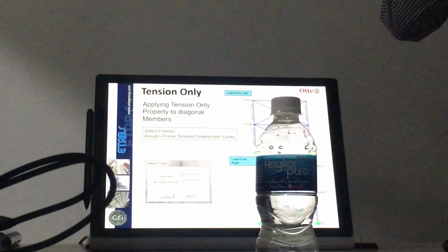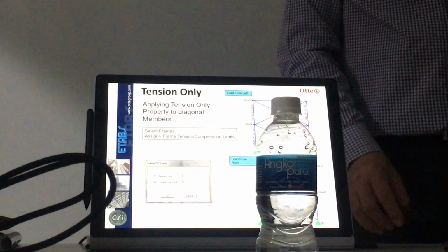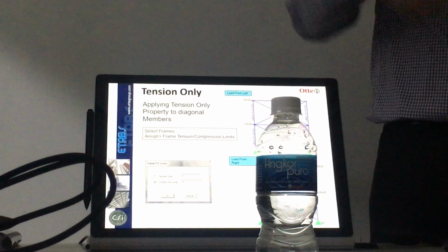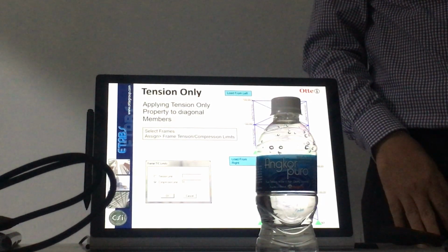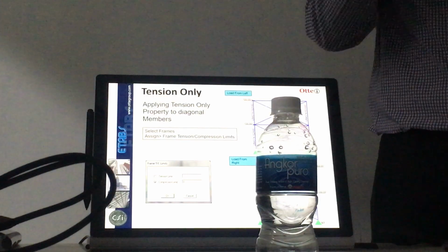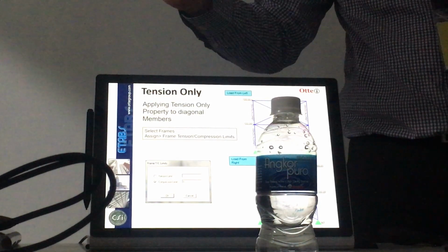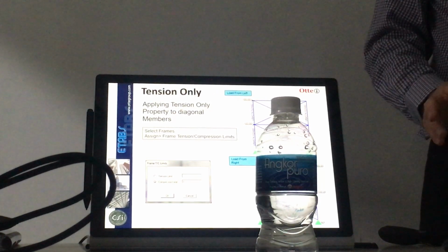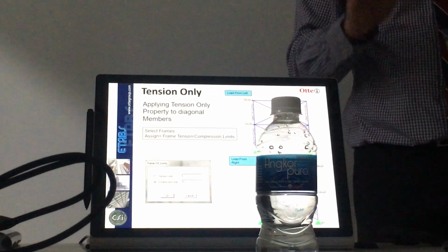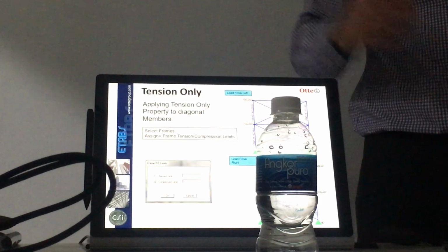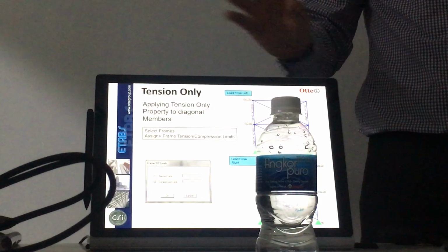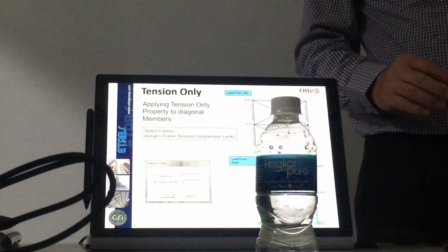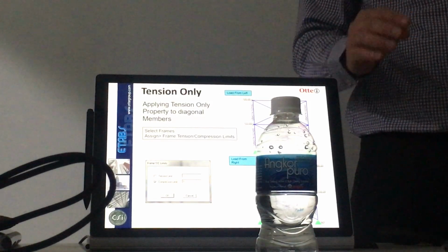What do I mean? Let me explain a bit more. When you design a frame, a factory, the factory has live load, has dead load, and has wind load, right? You actually, in a linear analysis, not direct analysis, I'm talking about typical analysis of a factory building, using the effective length method, you do a linear analysis. You actually don't analyze the building to take wind, dead, and live together. No. You look at the effect of dead load, you get one force out. Look at the effect of live load, you get another force out. And the third is wind load.